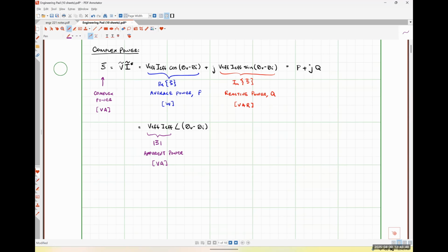Because the size of conductor that you use is dependent on a number of different things, like what type of insulation is used on the conductor, where the conductor is located, whether it's in open air, whether it's in conduit, whether it's buried in the ground, how many conductors are physically located near each other, because there is something called the proximity effect, where effectively there's electromagnetic interaction between the conductors that can cause them to carry more current than you're expecting. All of those things generally need to be taken into account when you're designing an electrical system. So we'll dip into that in a little bit, okay?